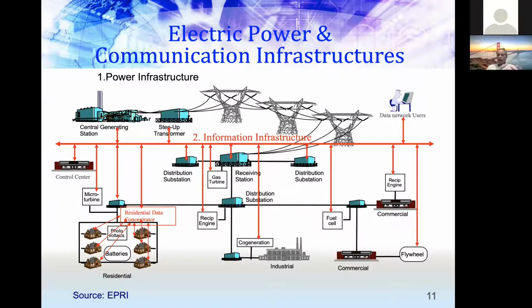Once it goes to the data concentrator, it is then transmitted to the substation using mobile phone GPRS network. The power company is renting bandwidth from the telecom companies to receive data from the data concentrator into substation. From the substation, power company has their own fiber optic network, physical network, substation to the control center. That's how the voltage information from my house is going to the control center and they can take action. So that part is new and it's happening. If you have a smart meter, there has to be some communication, like I just said, to make it work. Good, we can come back to that if you have questions later on.